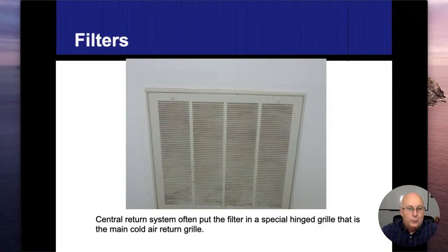And I've seen them anywhere from 25 to 55, all the way up to 55 to 85 degrees, all right? And I'm sure it would be even more than that, but those are pretty much the ranges that I see. So what that means is if I got a 70-degree temperature in the house and I got a 30 to 60 temperature rise, that means I should be between 100 and 130 degrees.